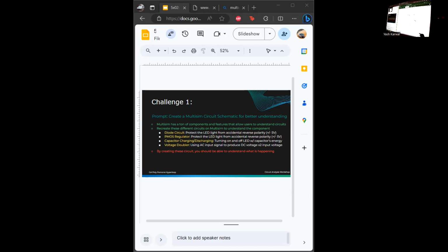There is a voltage drop. On the green side, it's 5 volts, which is your power supply. On the other side, it drops to 4.3. So the diode is charging you some voltage, like I explained in the slides. Now what if we change this to -5 volts? Here, let me just flip it. Let's pause it, take it out. Oh, it just killed the whole thing.